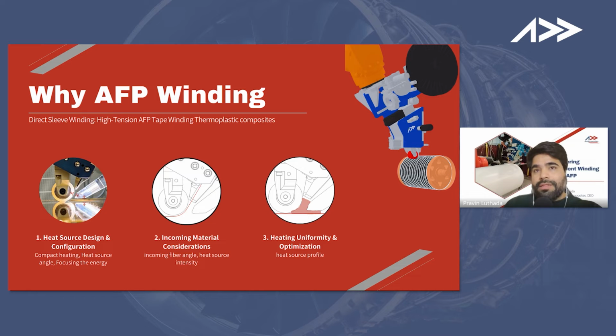And there is a possibility, because of the circular nature of the geometry, you're able to achieve, I would say, on top of an existing one, to wind and in situ consolidate the sleeve. So there is no secondary process. With thermoset, there's always a curing step, and with this capability, there's only a single step process that you're able to optimize quite a lot.